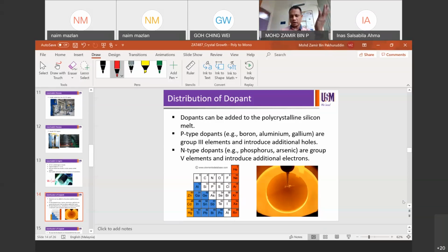So you've got the basic understanding of how doping works, right? Remember the four neighboring bonds of silicon. When you put phosphorus into the lattice, you end up with one free electron wandering across the lattice and giving conduction. On the other hand, if you put boron in, you lack one bond, so that will be a vacancy or a hole. It will also wander across the lattice, giving p-type conduction.